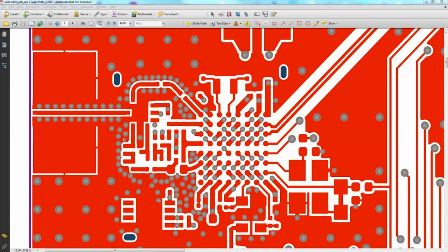They are simply the traces on a PCB and depend on the length and the frequency of the signals passing through them. So even though we might look at this layout here, we have a transmission line here and also over this side that deal with the antenna and the radio frequencies. We also have transmission lines for the clock frequencies here, as well as perhaps high-speed data or differential pairs. All of them have to be thought of as transmission lines for our purpose.